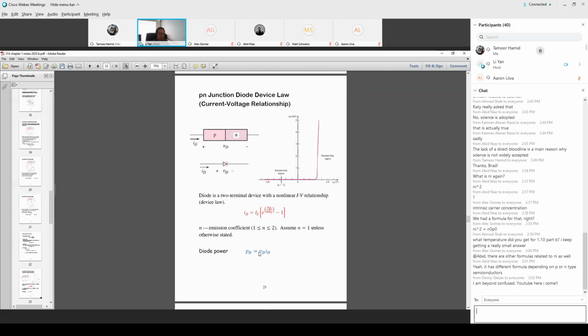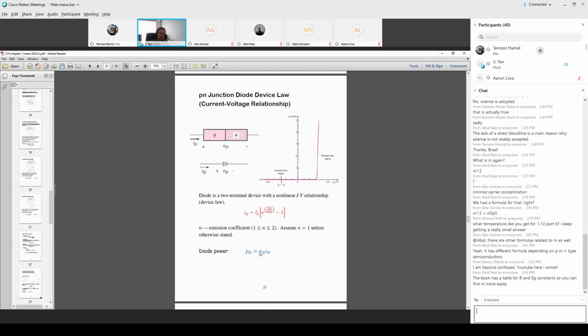You learned from 306 a very important convention called the positive sign convention. When you arbitrarily define the voltage polarity or current direction, you have to make sure the voltage-current relationship follows the positive sign convention properly. Sometimes you can put a plus sign, like Ohm's law, and sometimes in Ohm's law you need to put in a negative sign.